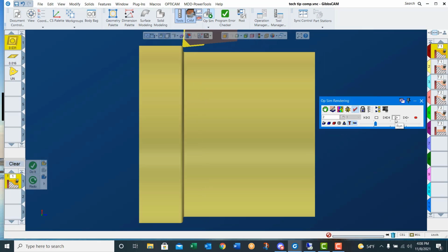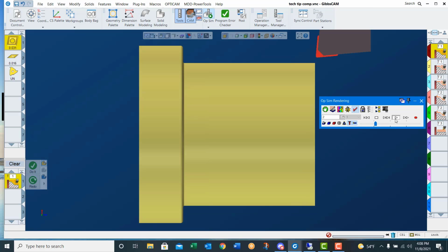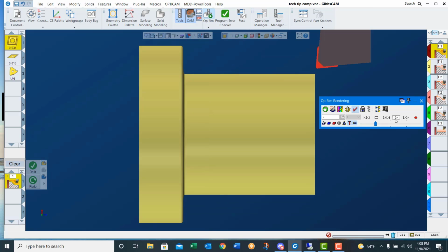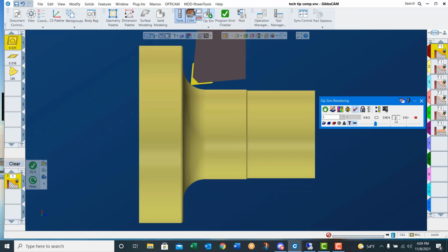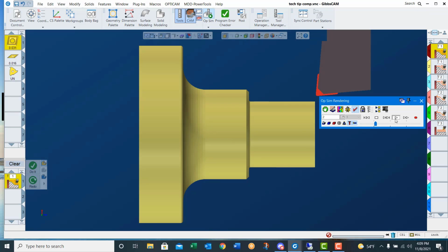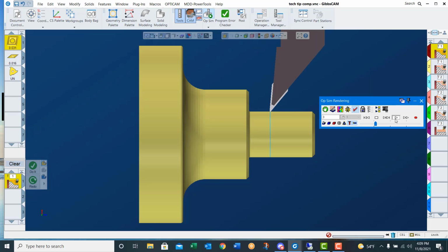In this month's Tech Tip, we will demonstrate how to use and save processes. Saved processes reduce the amount of time needed to program a part and allow you to save custom tools and tool holders along with information such as stickout length and comments. All speeds, feeds, and depths of cut will also be saved in the process. This makes for a more consistent look to your programs.